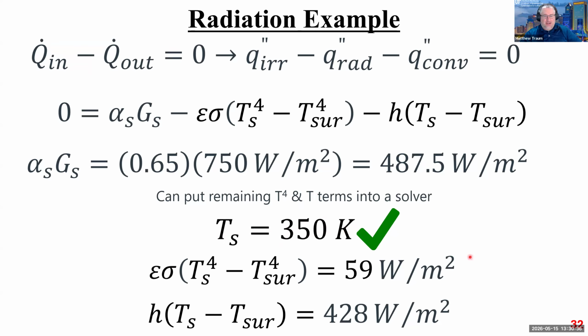For this problem, yes, but you probably want to go back and check. 50 degrees Kelvin is a big temperature jump. So the emissivity might have changed enough that you need to go back in and recalculate, right? And it would show up right here in your calculation. I didn't do it, but you could if you wanted to be really, really precise with your value.